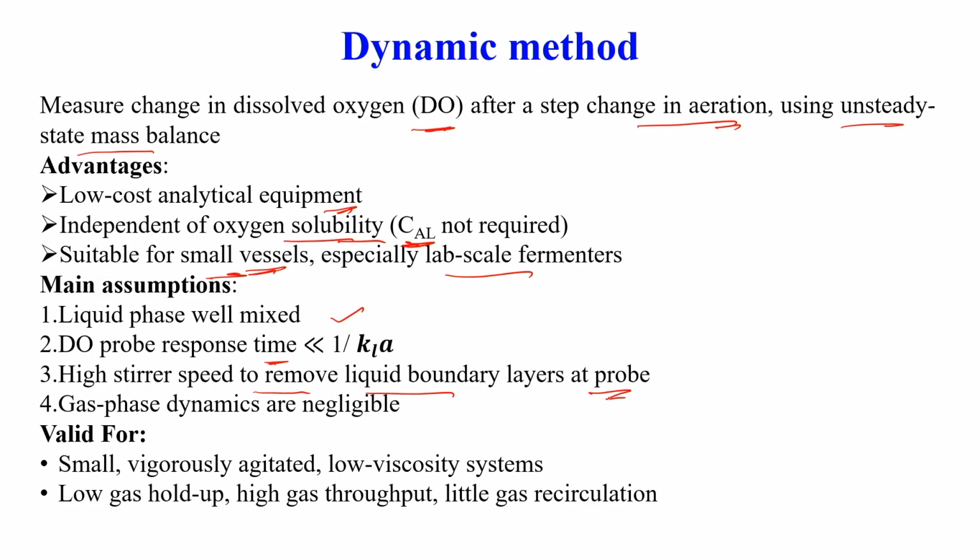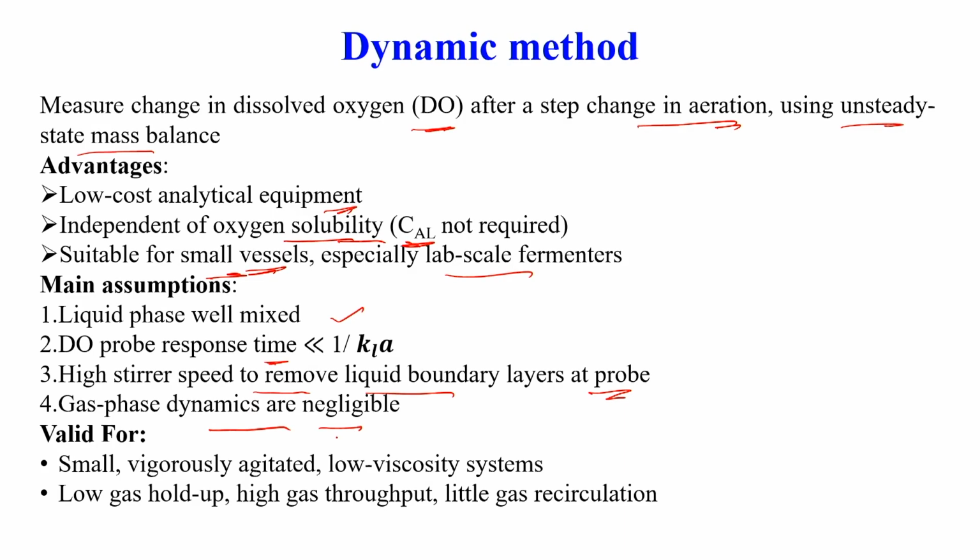So, there may be formation of this liquid boundary layer or liquid film at the probe also, and we are neglecting the gas phase dynamics. This method is valid for rigorously agitated and low viscosity systems. It also requires low gas hold up, high gas throughputs, and little gas recirculation.